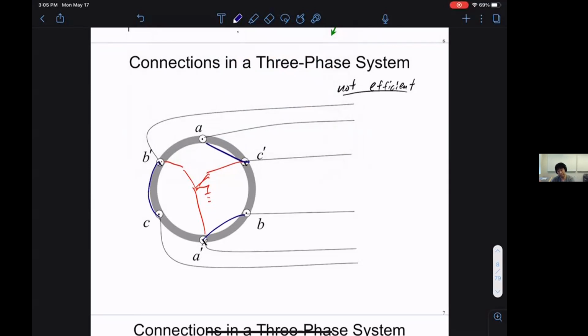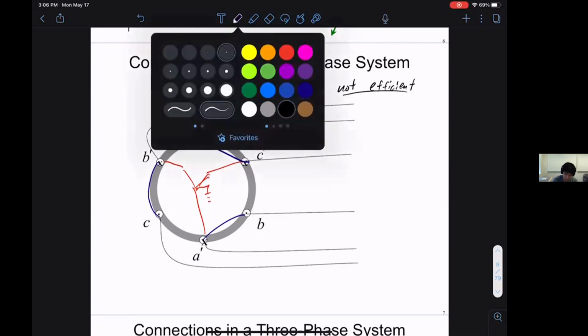One is you ground them out. Second is you connect them internally. So you don't connect, for example, A to A phase, but you connect A to C, B to A prime, and C to B prime. And this turns out will also work. So these are the two possible strategies we can have, and we'll be going through them in detail.